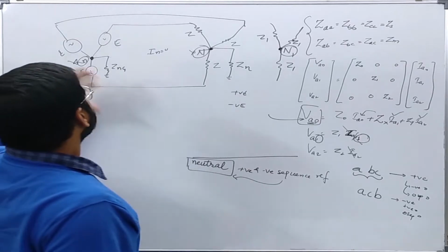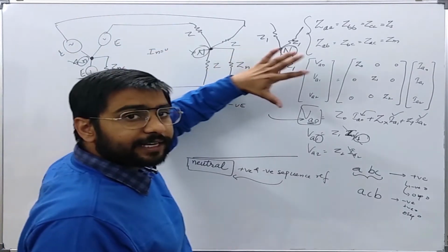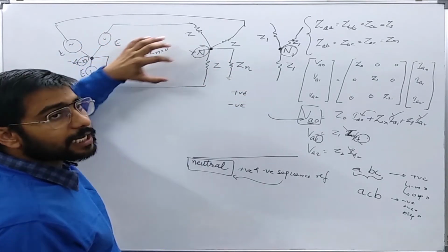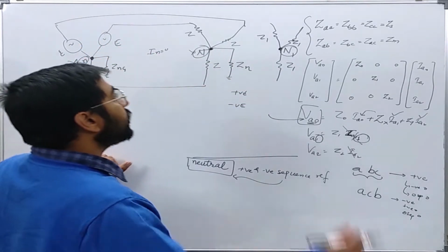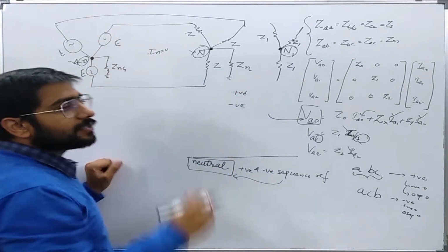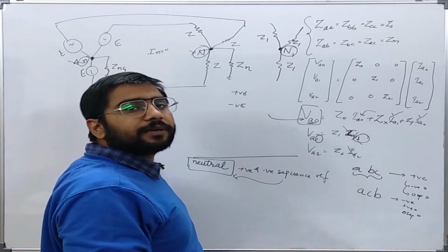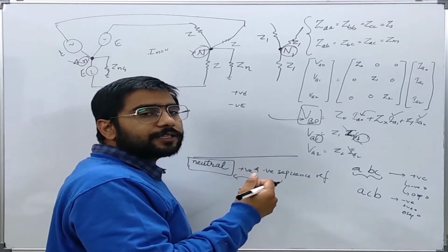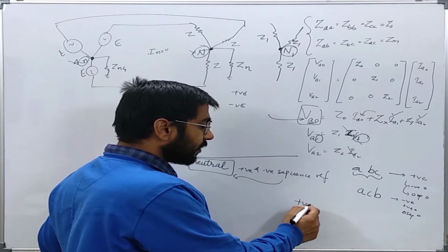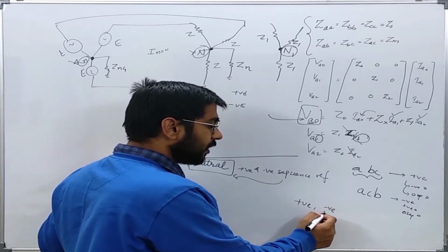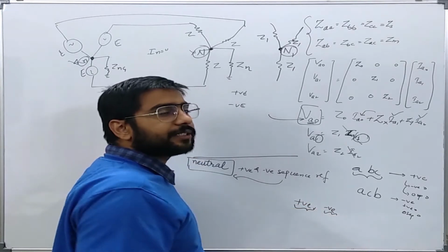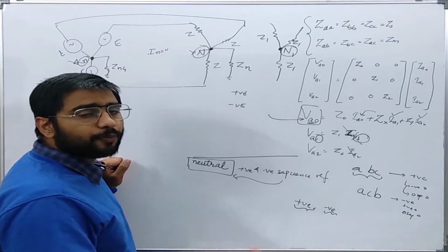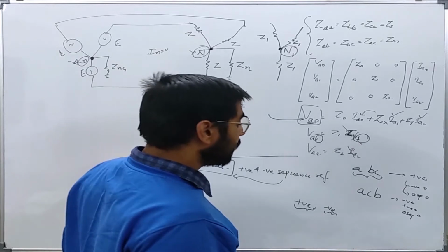Okay, so everything is quite the same. However, what happens in the negative sequence network is that we usually change the impedances offered by the rotating machines. As we have seen in our previous lecture, the positive sequence impedance and the negative sequence impedance offered can be different in rotating machines. However, these are not different for static components like transmission lines and transformers.